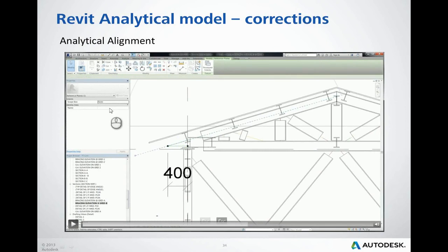And what's important, after creating reference planes, it's a good habit to name them, especially if you want to use them in different kinds of selections for projections, because the selection projections are based on the names of the axes, grid lines, and also on the names of reference planes. So it's important, if you want to use them for projections, to name such reference planes.